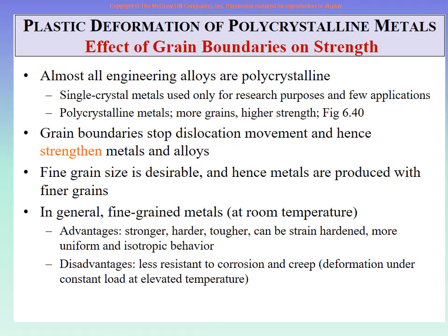Now, what we want to know right now is that when we do plastic deformation, when there is a metal, you apply load, nothing happens. You apply more load, nothing happens. After you apply a certain amount of force, it starts to deform. But then when you remove the load, it goes back to zero deformation. That area is the elastic part. When you increase the load so much that it deforms, and when you remove the load, it does not go back, it is now plastic deformation.